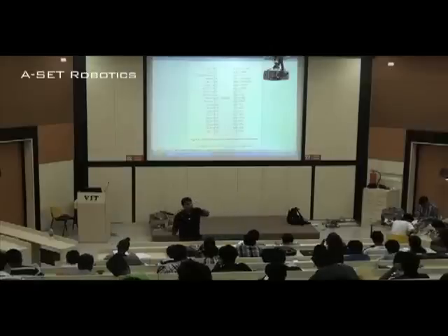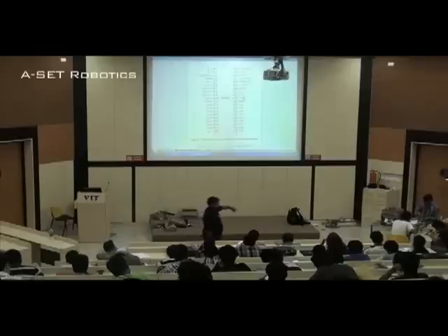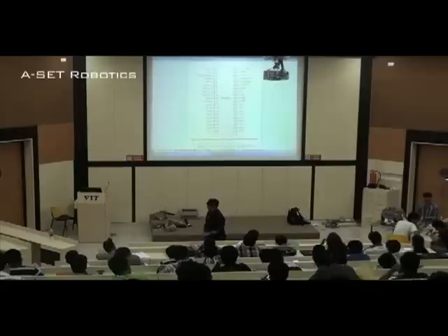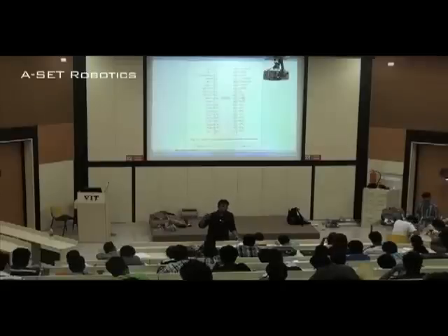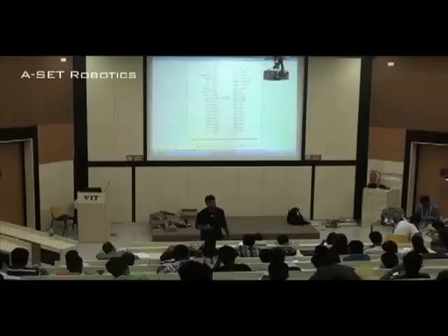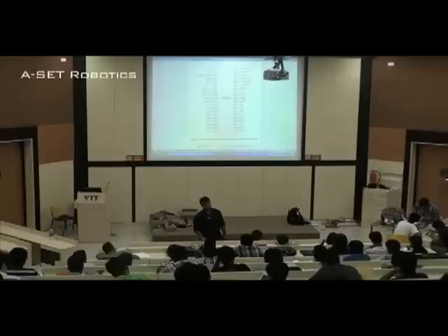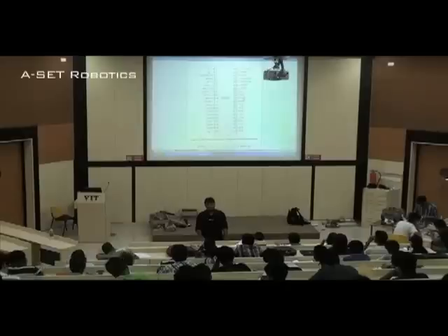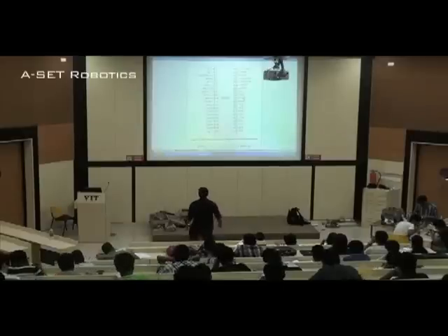Whenever ALE is low, data is being transferred, and whenever ALE is high, address is transferred. There is a latch outside this microprocessor. A latch is a group of registers, and it is activated and stores the address temporarily. So that is called Address Latch Enable.